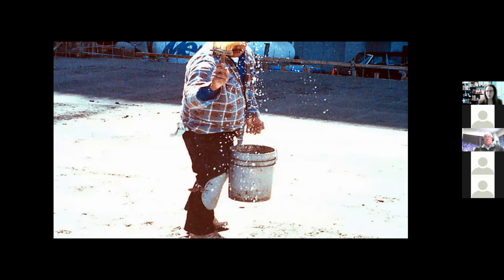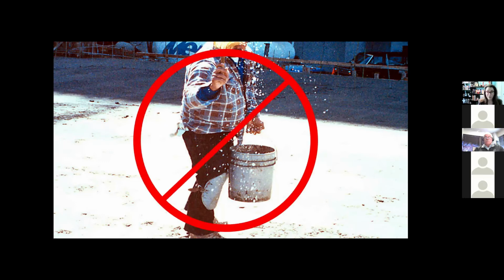So it's important to leave the concrete alone if you're doing any type of monomolecular film and not finish it into the surface where you'd increase the water cement ratio at the surface. Any increase in water over a certain amount is going to make it more prone to dusting. So this is a big no-no. I know it happens, but it's not what we want.